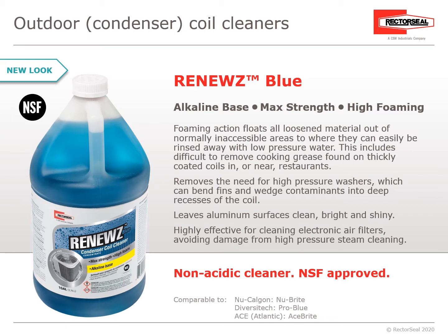It removes the need for using high pressure washers, which can bend the fins and wedge contaminants deep into the recesses of the coil. It leaves aluminum surfaces clean, bright, and shiny. It's highly effective for cleaning electronic air filters, avoiding damage from high-pressure steam cleaning.